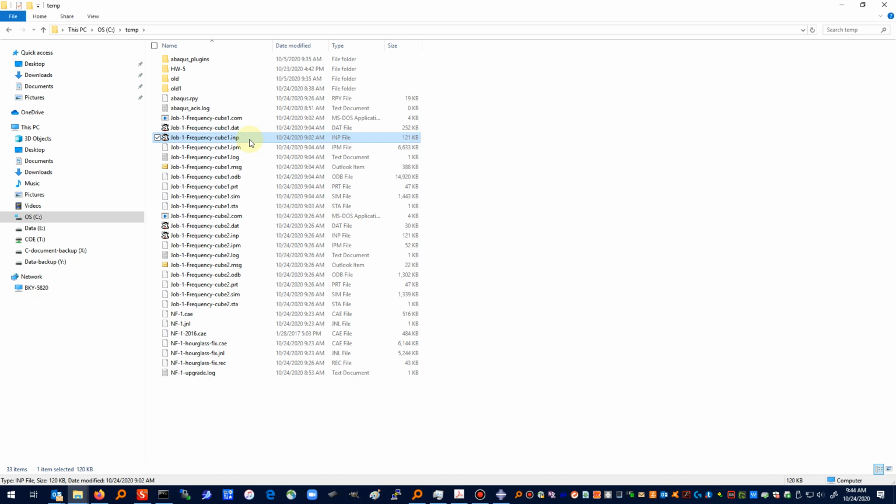You can run this from the command prompt. You can import this into other finite element codes or things like HyperMesh. Okay, maybe not all the features will import into a different finite element code, but enough of it, the geometry, the nodes, the mesh in particular, will be able to be imported without a whole lot of problems. I would keep this if you're going to archive your analyses.